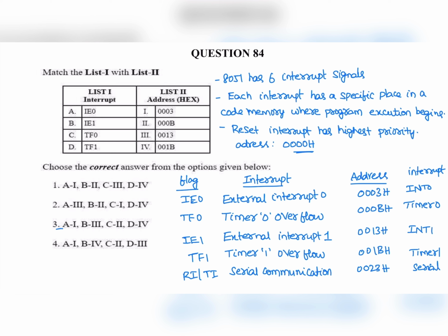For IE0, it is 0003H. For IE1, it is 0013H. For TF0, it is 000BH. Next, TF1, it is 001BH. Correct option is 3.